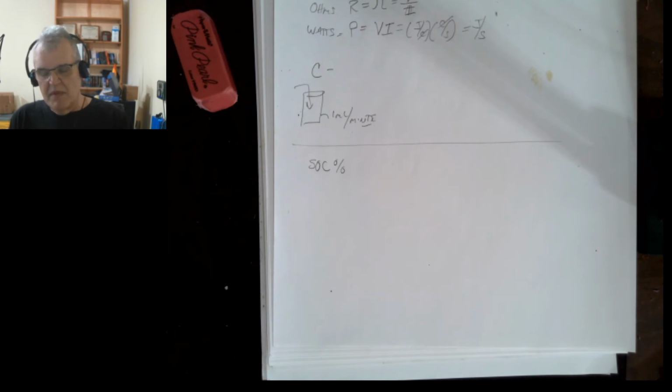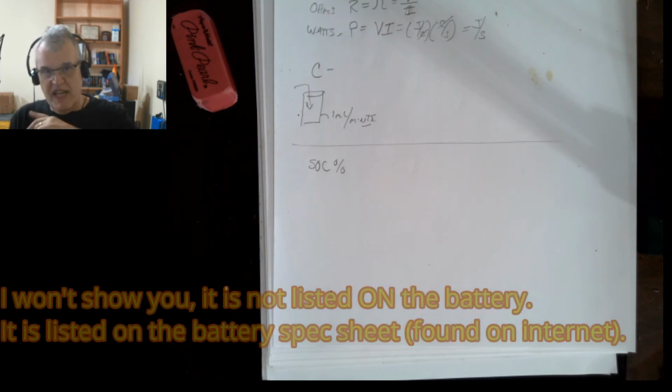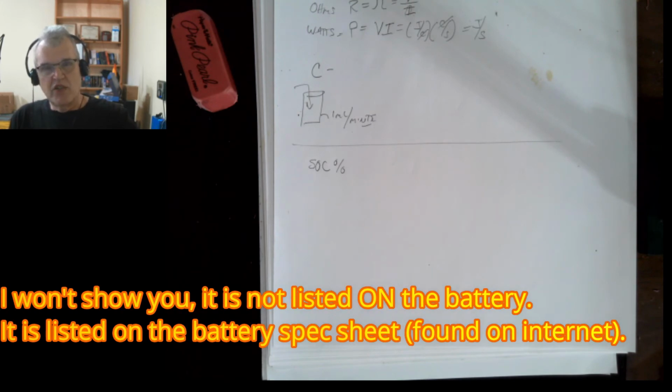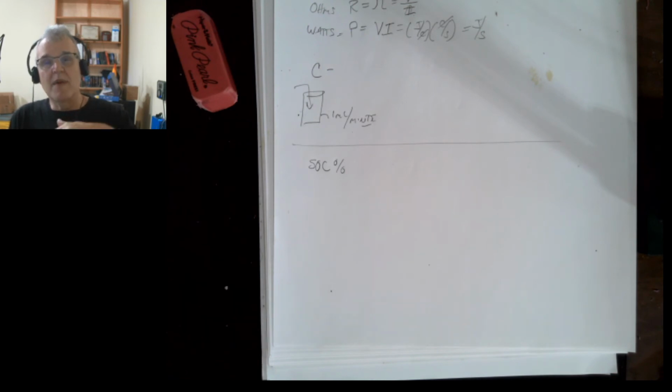And then the final thing is the maximum continuous discharge current. Batteries will have that rated on them, and I'll show you on 18650 batteries. I'm using the LG M26 batteries. The manufacturer lists them as 2.6 amp hours of capacity and 10 amp maximum continuous discharge rate. That would be the maximum rate of discharge the battery could do without causing catastrophic damage to the battery. You would never want to get to that, because it will cause damage and heat the battery up significantly due to its internal resistance. But that's the maximum that could be done.